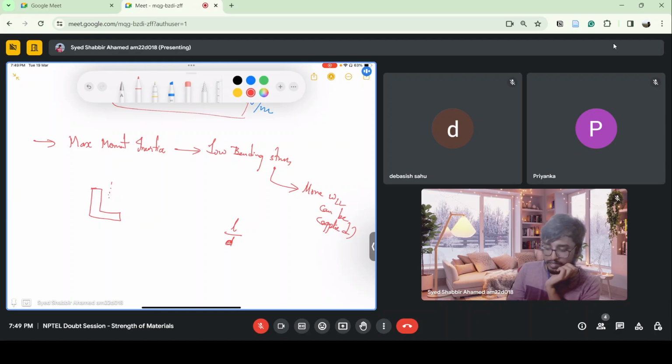So if this depth increases, this ratio will get decreased. So if depth increases, what happens is that the section is not perpendicular to this, because shear also comes into action. So the understanding which we have got is limited to the case where depth is small. If the depth increases, we have to go for another beam theory, which is Timoshenko beam theory.